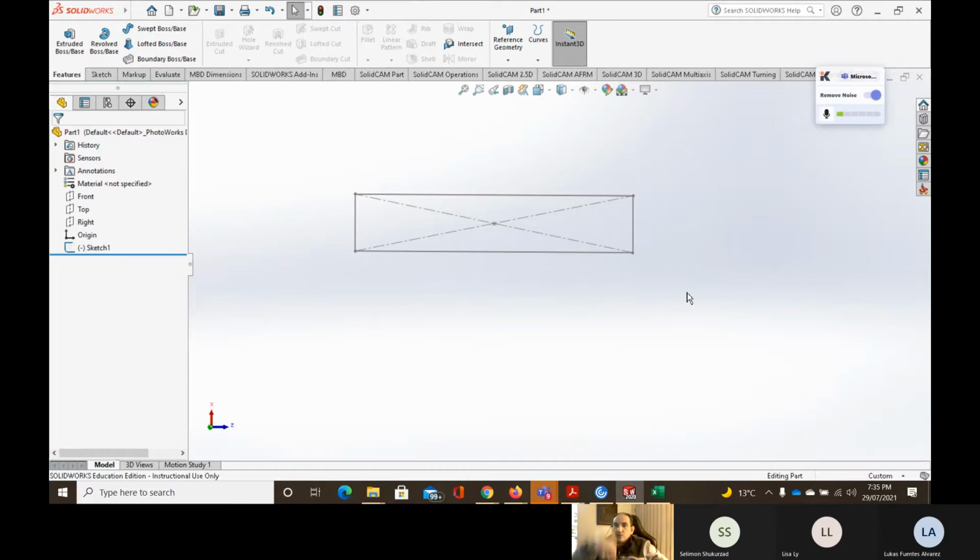If I'm going to take a look to the center of this tool post, this is what the machine in general knows as its datum point. So we usually write down the G51, for example. I think it's G51. Then you write down that the X is going to be offset from this point by this value for the X, this one value for the Z, where is going to be this location. And then all the points are going to be referenced to that location.